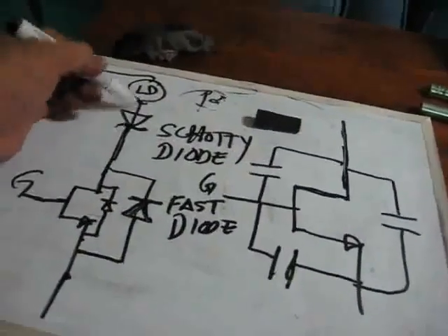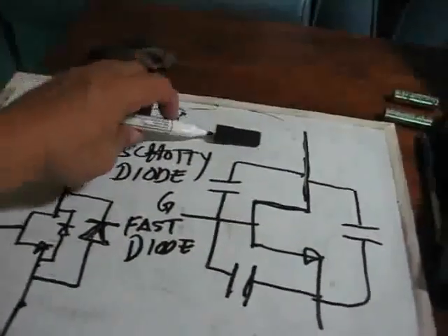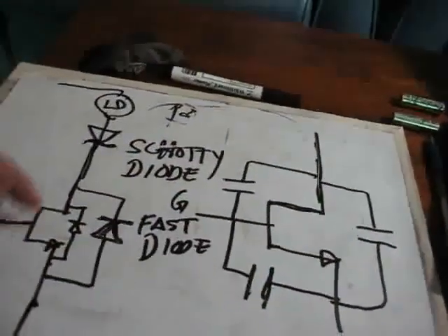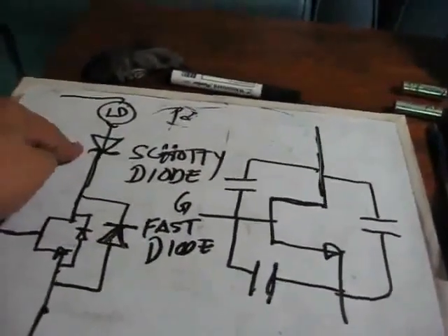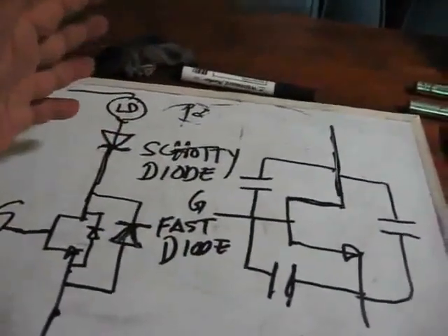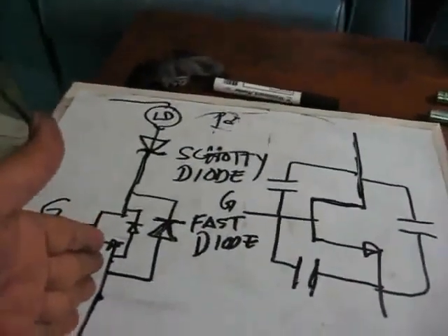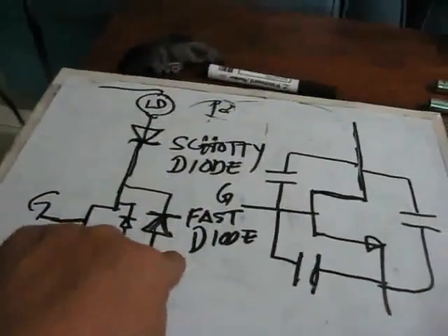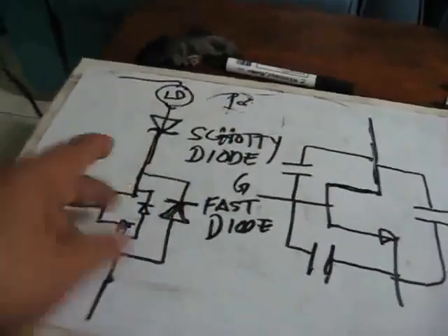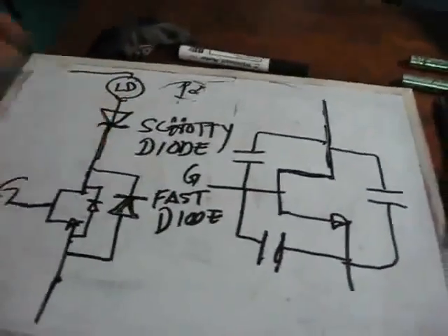You can put it here just in case there is a very fast reverse polarity of something like ambient, etc. This will help, because if there is a fast reverse polarity of current, this will delay the power going in, so that the diode has enough time to catch the reverse current going through here. So it can create a delay.